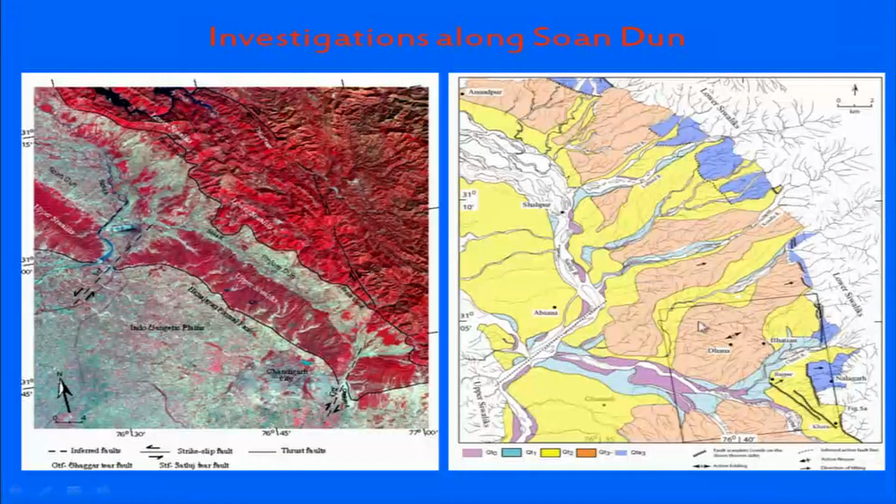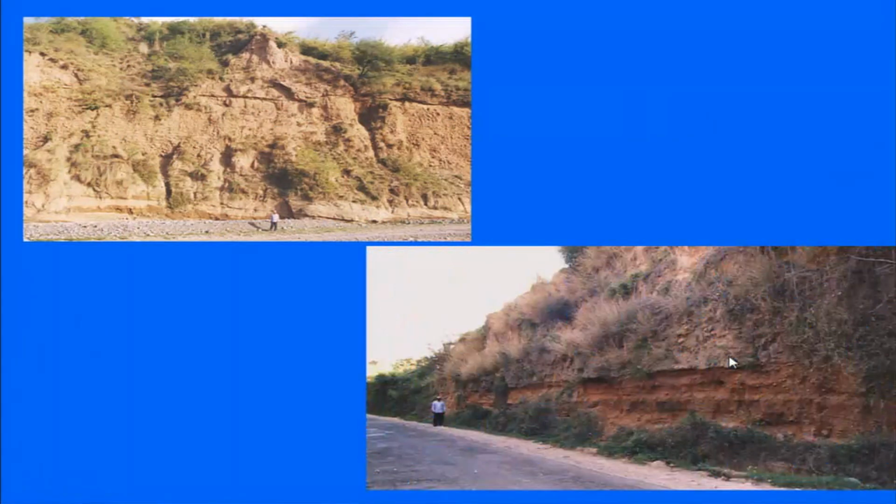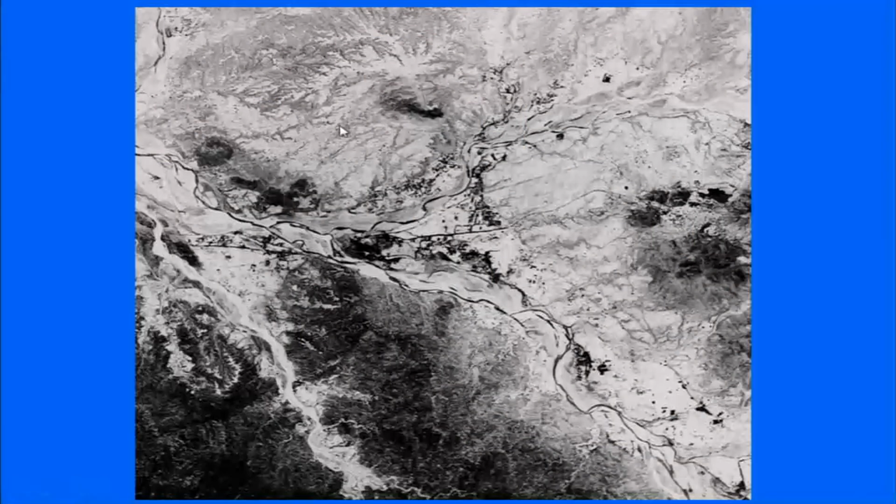Now if you look at this area, the region is occupied by the Shivalik succession as well as the younger Quaternary succession. This is the succession which is occupied by the terrain. In the close-up of the area which I was showing in the previous slide, the drainage is flowing in either direction. So this portion is a warped portion, which is because of the fault line marked by the arrows here. This fault, along with the deformation, has resulted in the warping of this area.